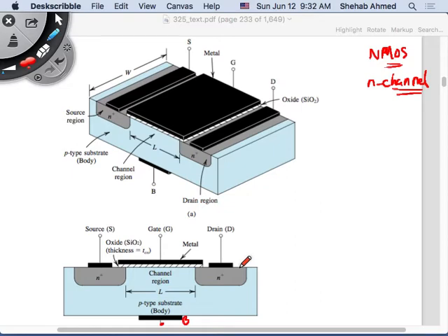For now, think of it as, we have a P-type wafer, and then I also have N-type material as well. This N-type material is not part of that substrate. I will add it to the substrate, so I will grow N-type material on this substrate.